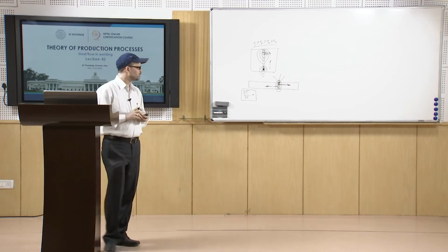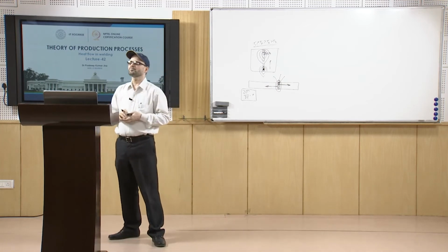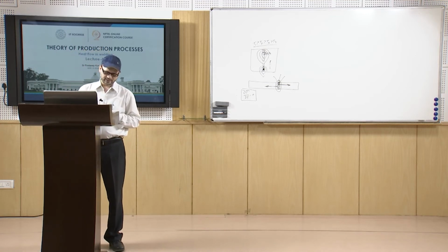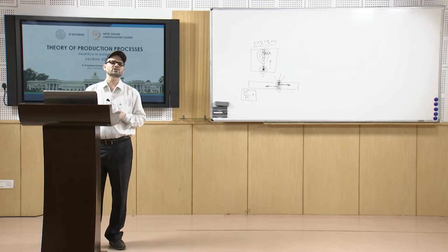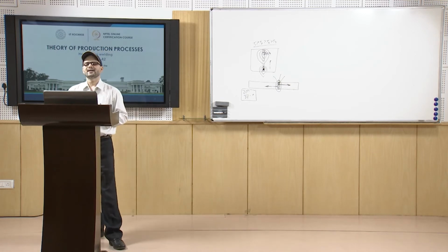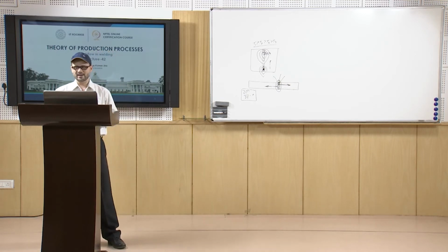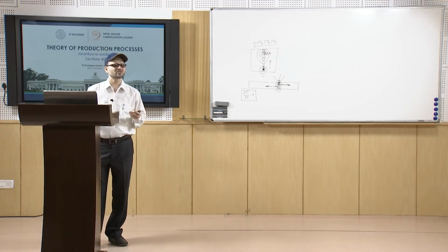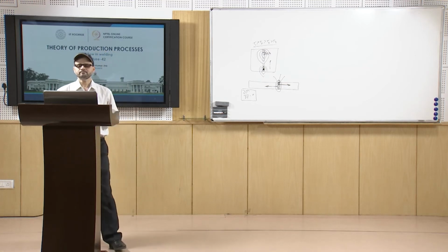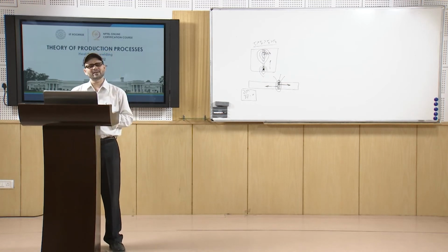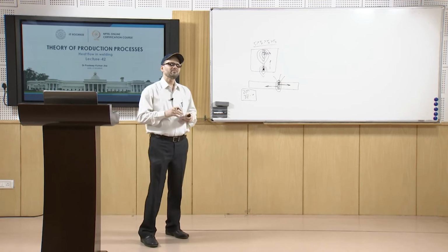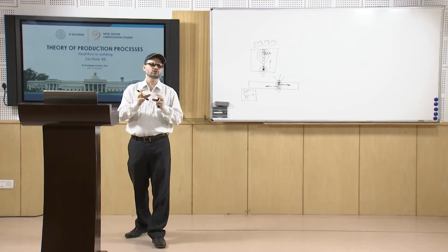Now, if you talk about the 3-dimensional Fourier law, the Fourier equation of 3-dimensional heat conduction in solids, what we get is dou square T by dou X square plus dou square T by dou Y square plus dou square T by dou Z square, it will be nothing but 1 by alpha dT by dt. So, that is what the Fourier equation of heat conduction is, where alpha is nothing but K by rho Cp. So, that is what the Fourier's law of heat conduction is, but in this case you have a moving source.